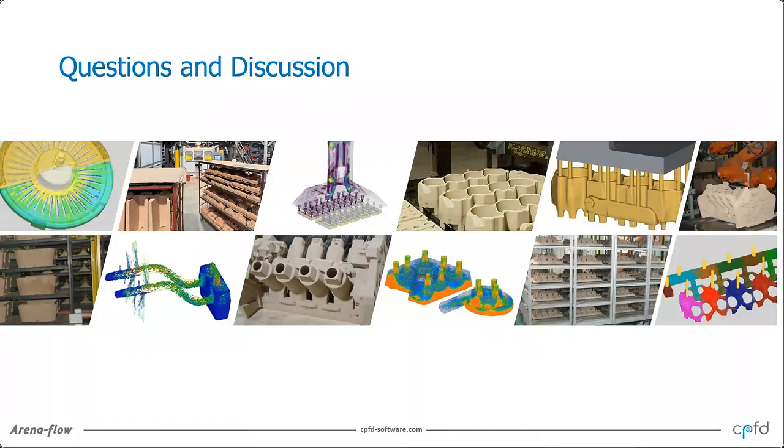You have your binder in cold box, it could be aged. Your vents could get clogged. And so which case are you simulating? The first clean blow, the 20th blow, right before you clean your vents. And so first of all, if you have a 5% scrap, we probably don't want to simulate the 19 out of 20 that are good cases. You probably want to solve that 5% that are not. And so that's one of the things the flowability model is used for.